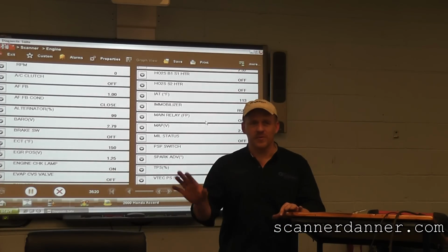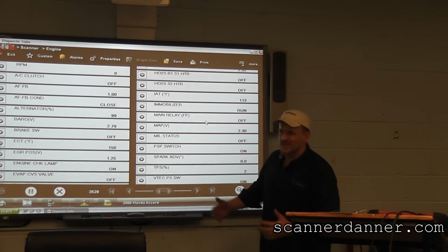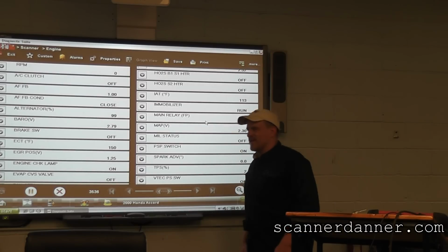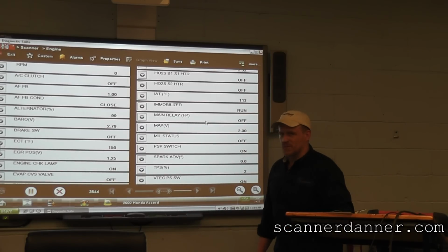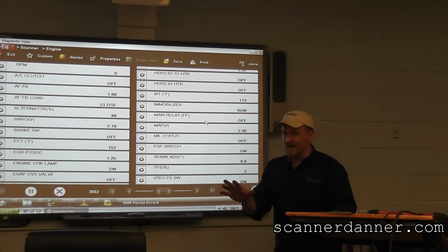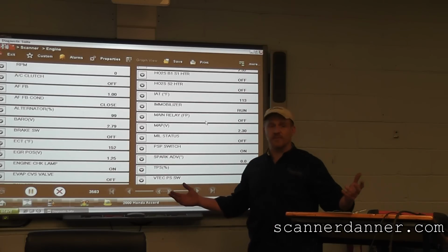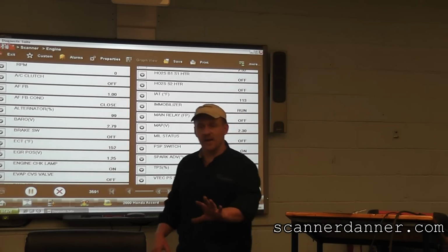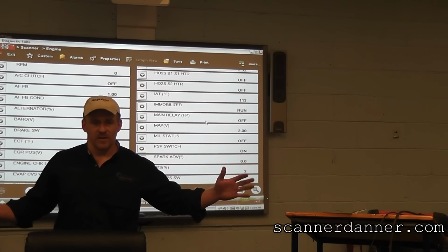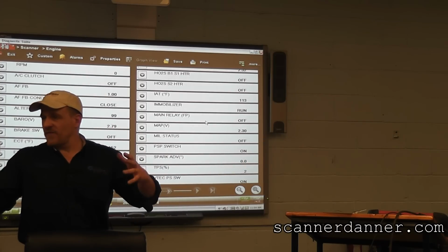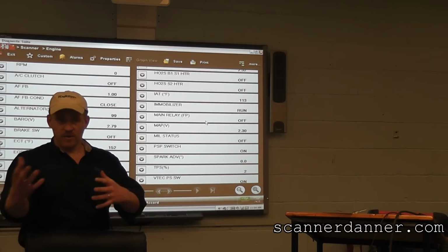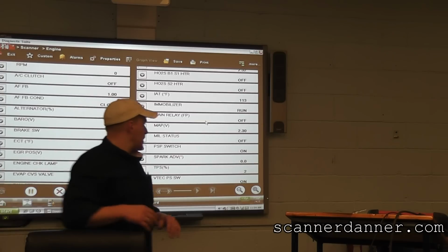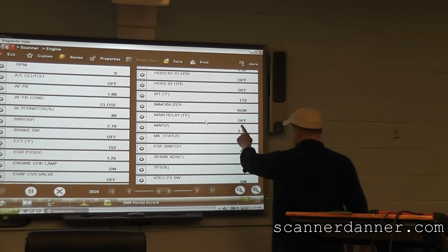I'm going to walk you through this, maybe as quick as I can, and back up through the detail. I don't know. The hard part about doing this live is which way do I want to take you. There is not one way to do this. That's the conflict within my own mind, which method do I want to show you? Ultimately I'm going to show you every one that I know. It's right now in front of you live. Which one am I picking? I want to verify MAP sensor, wiring, computer, okay? That voltage never changed. Don't like that.